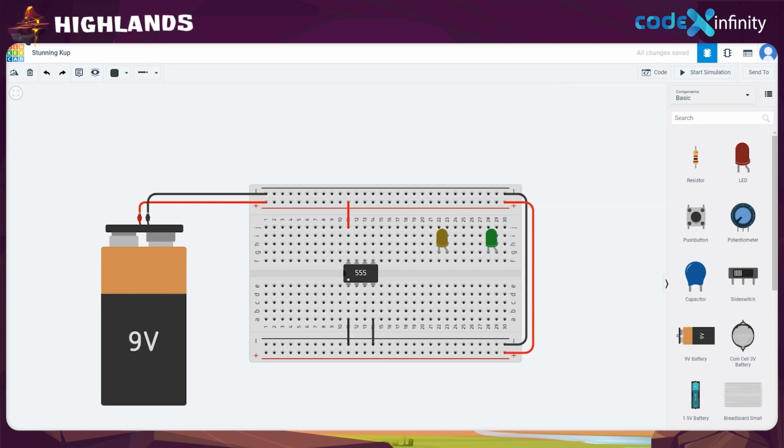What about connecting the LEDs then? But hey, we can't directly connect the LEDs. You see the big battery? That's the one powering up the entire circuit. If we directly connect the LEDs, they will explode. That's an immediate red flag, pal. So we need something to limit the current flow. Know any components appropriate for the job?